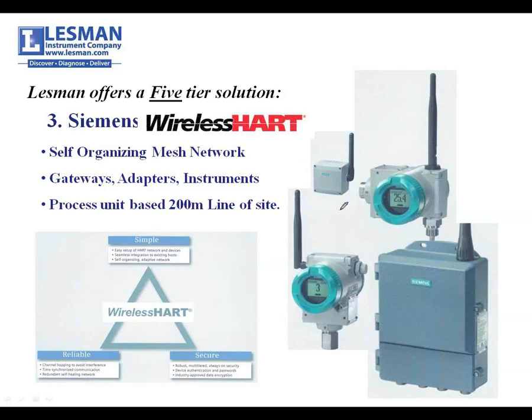So if you have multivariable transmitters, which are capable of giving you a variety of information, you can only get one thing back on your 4 to 20. Well, if you wire in one of these adapters and communicate back to a base station, now you can pull all the information that is available from that device out. So if you are pursuing a predictive maintenance strategy where you're watching valves age or pumps wear, this is a great strategy to do that.